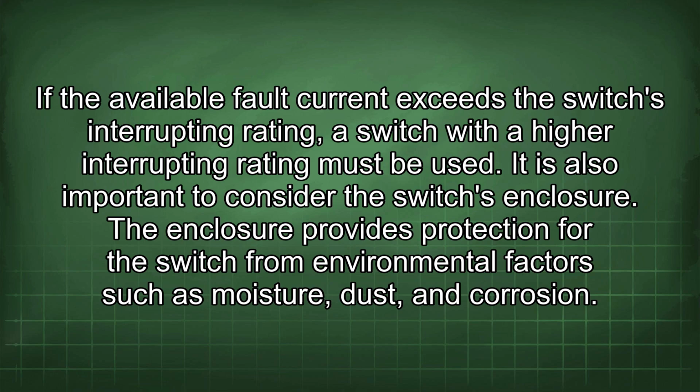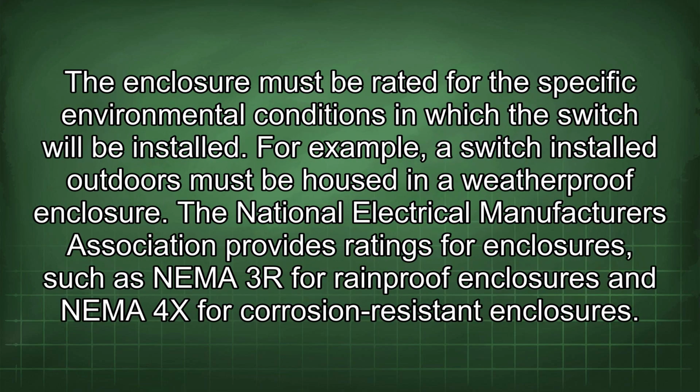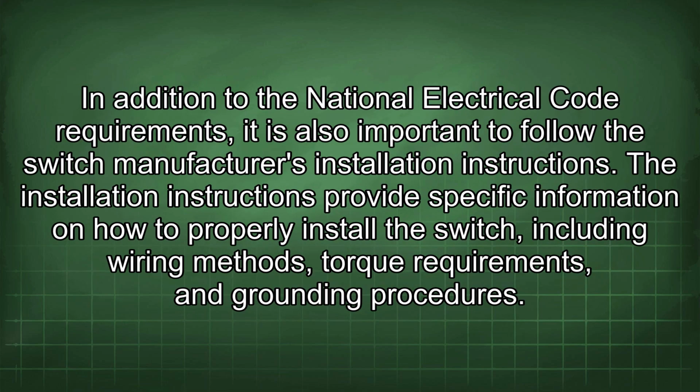It is also important to consider the switch's enclosure. The enclosure provides protection for the switch from environmental factors such as moisture, dust, and corrosion. The enclosure must be rated for the specific environmental conditions in which the switch will be installed. For example, a switch installed outdoors must be housed in a weatherproof enclosure. The National Electrical Manufacturers Association provides ratings for enclosures such as NEMA 3R for rainproof enclosures and NEMA 4X for corrosion-resistant enclosures.